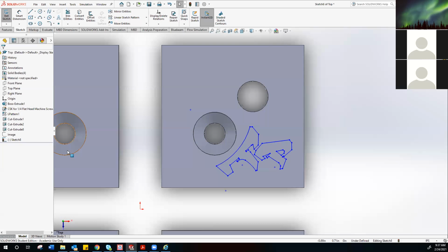Oh, you tied it down there, did you? Okay, well, you can do a couple of things if you hide your constraints. Okay, so what you have to do, that's why I don't hide my constraints. You tied it to the edge. So you right click, delete that. Then you can move this point. But you've got these that put the loop. You have a lot of constraints. So you need to slide the text up here, right? Just for the line. And you trim forces.